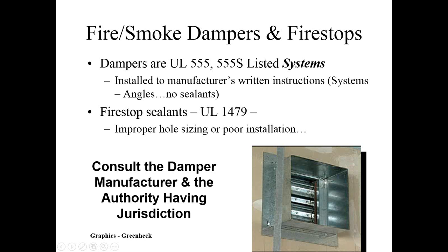It's an impact test, similar to the hose stream test, in addition to the hose stream test, so it's a second test, believe it or not, to make sure that things that fall in a fire, ceiling tiles, pipes, big, huge pipes such as cast iron and steel, if it hits that duct, breaks it, and hits the duct, will the breakaway connections let loose so that the damper stays in place in the wall? Very important stuff.